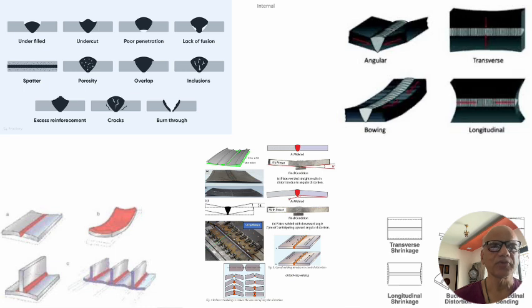And you can see from the figure itself, and this is what in reality also many times we see. The welders who are not able to see the profile of the weld through their screen, they'll end up, or the parameters are bad and they're using excessive arc length. This is what will happen. It will spread, it will have lot of deposition only in the center portion, but the rest of the area is getting melted and flown, and that's where the width goes up.